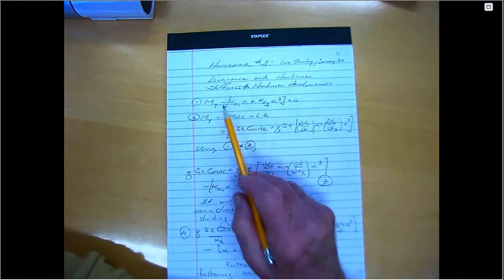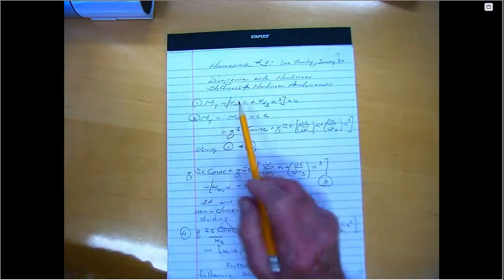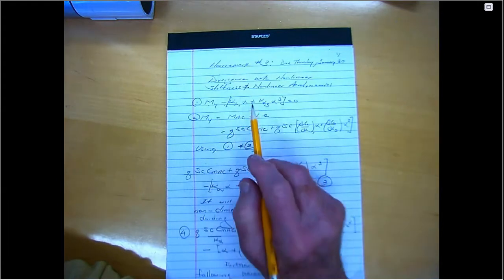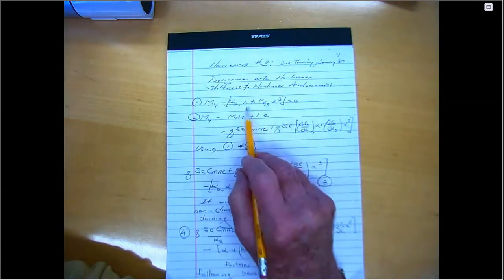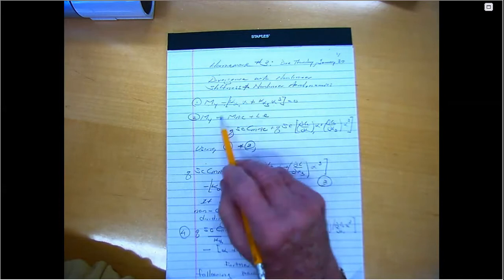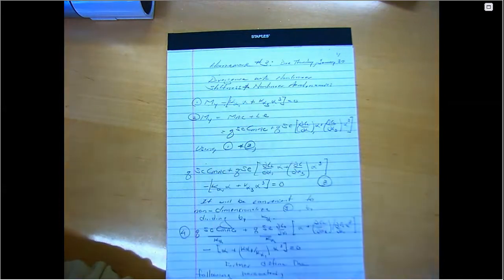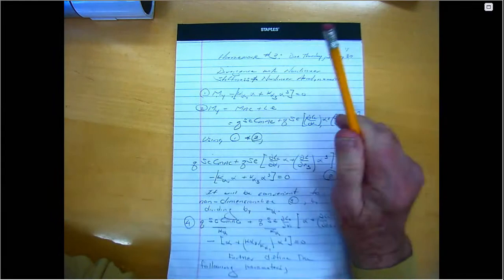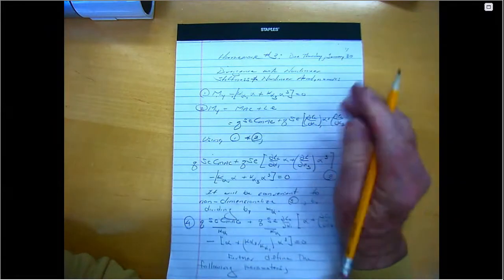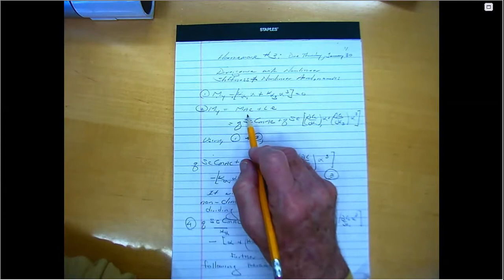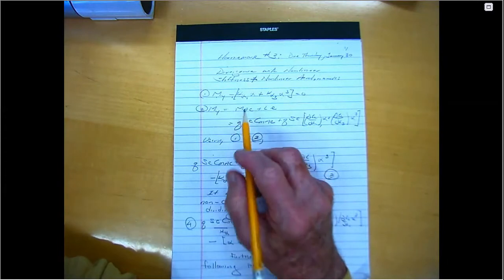That's equation 1. This is the aerodynamic moment, which we'll elaborate on, and this is the nonlinear spring, which generates a structural moment, and they have to balance, right? By convention, the aerodynamic moment is separated into two parts: a moment about the aerodynamic center, which does not depend on alpha.